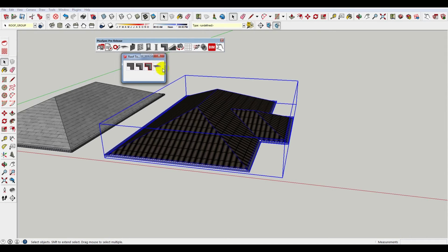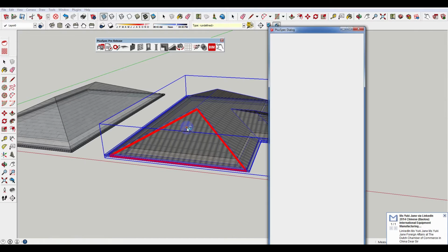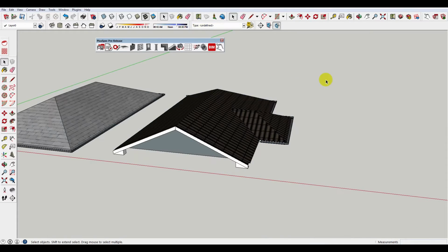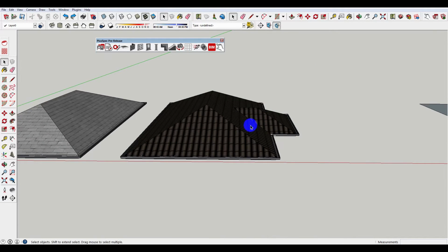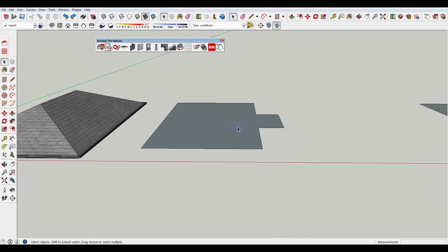I can go back and change these roofs at any time if I please. So I can say, okay, you know what, I actually wanted to have a gable down this end here, and I can select that, and you'll notice it's got a pitch here which is 90 degrees, and I've got an overhang of the gable. I'm going to leave it at both of that and just push enter, and now you notice I have a gable roof.